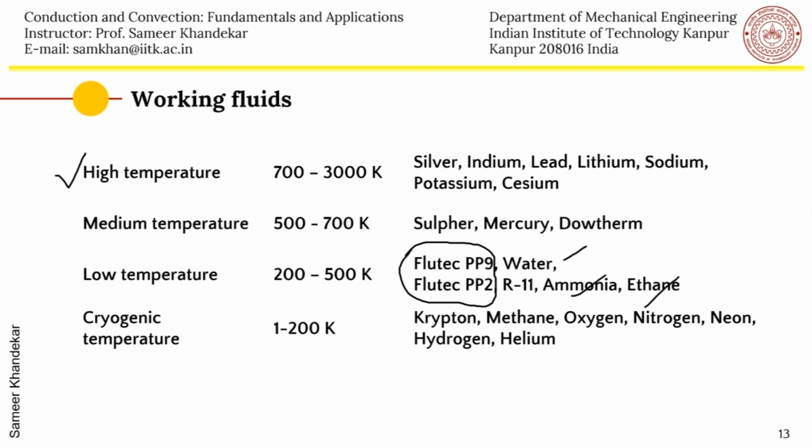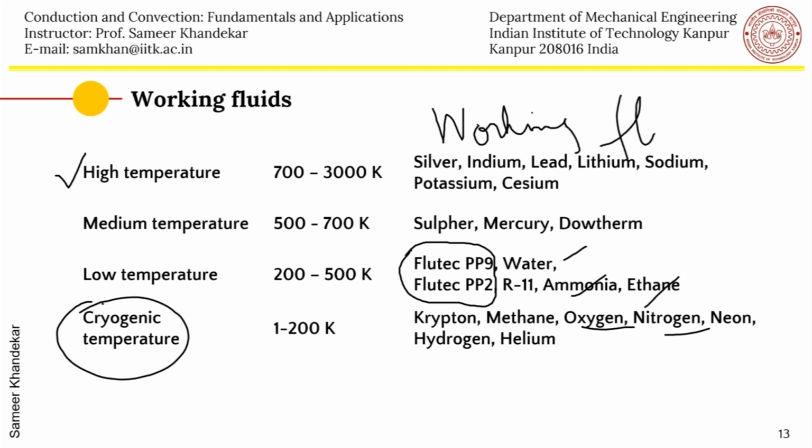And then, depending on its thermophysical properties, its freezing point and melting point and critical point, depending on the application, one can choose the right fluid for the right temperature range in which you would like to transport the heat or operate the heat pipe. Now, as you know, this particular fluid is inside the wick. So you have the container, you have the wick around it, and then the fluid is all saturated inside the